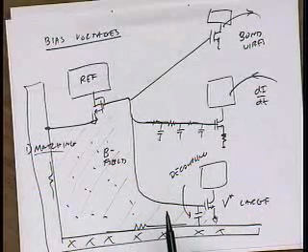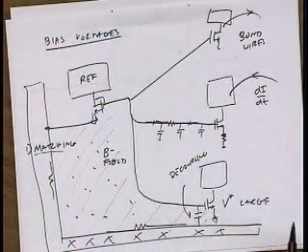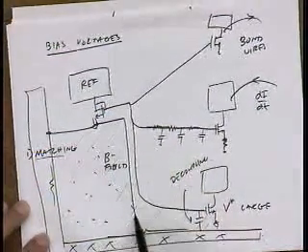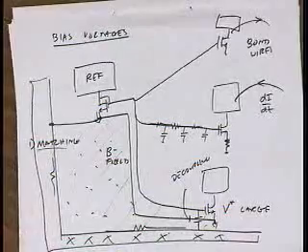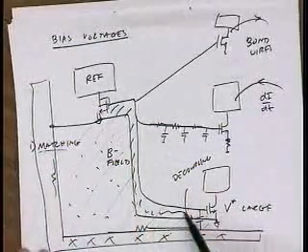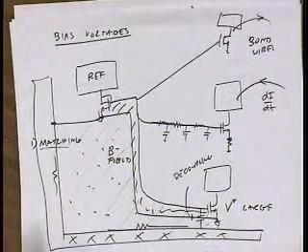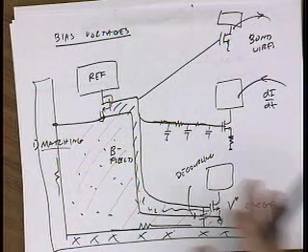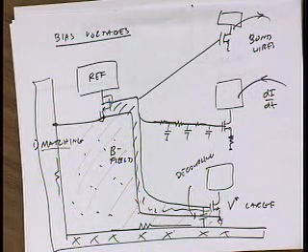Okay? Could you reduce the loop area by routing the lines together? Yeah, the solution is very simple. If you're just willing to take two wires, you're done, right? Now the loop is very small, and so you're less susceptible to pickup. And in fact, you can put these wires very close together, right? So there could be almost very tiny area. You can reduce the area by several orders of magnitude. Okay?